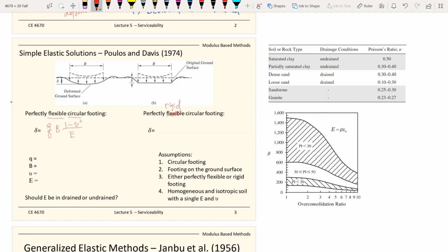So it is a small strain behavior, because the soil behavior follows a stress strain curve. It highly depends on the deformations. So the response of our soils depends on how much deformation we are talking about. This is a very small strain deformation, because the elastic modulus applies in the elastic range of soil, which is very tiny deformations, on the order of 10 to the negative 4 millimeters, where you have elastic behavior. So the formula here is the elastic solution.